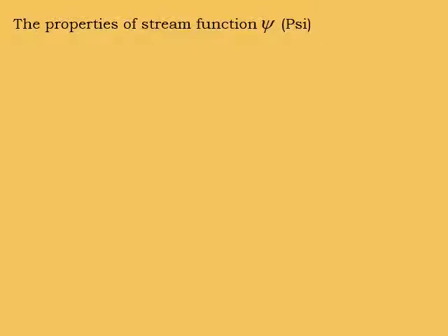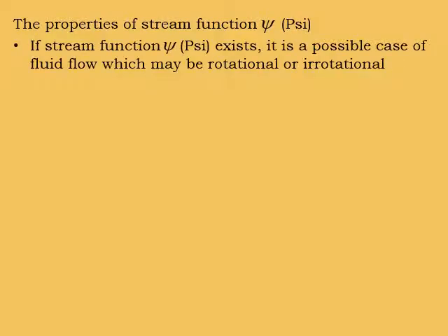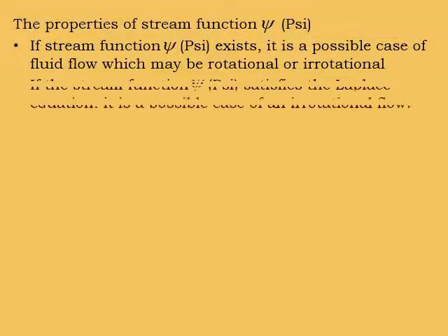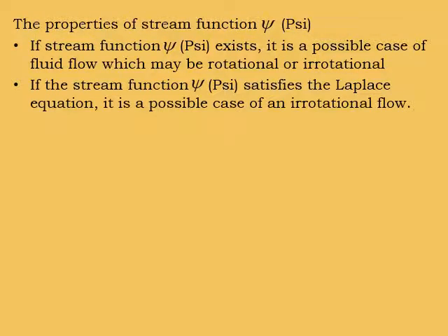So next, what are the properties of this stream function? If stream function exists, it is a possible case of fluid flow which may be rotational or irrotational. If the stream function satisfies the Laplace equation, it is a possible case of an irrotational flow. So these are the two properties of this stream function.